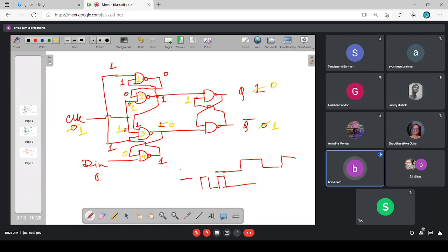If you go to the data sheet of any JK flip-flop or SR flip-flop, you'll find that it is quite complex, and a lot of different types of feedback are involved. Here I have two different feedbacks. One is this feedback, and the second one is this feedback. Apart from the internal feedbacks of the latches, each latch has an internal positive feedback. Apart from that, between this NAND latch and this NAND latch, I have two special types of feedback.